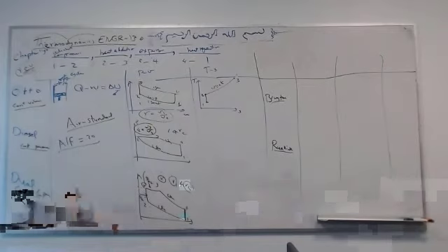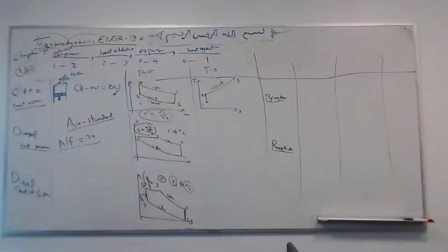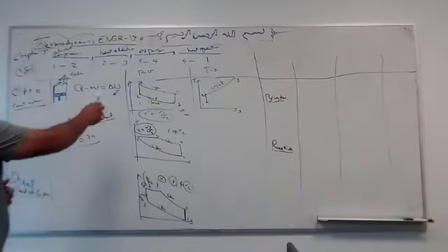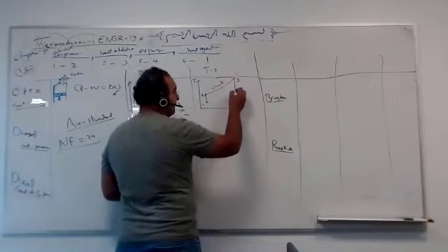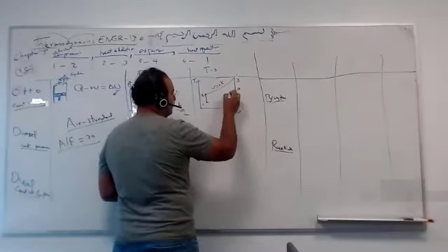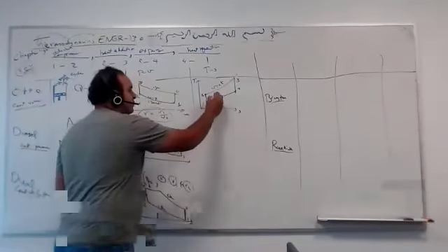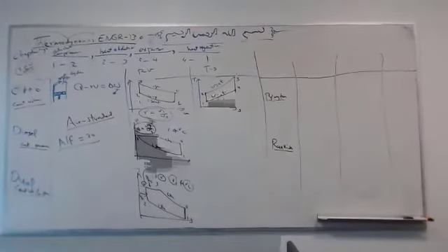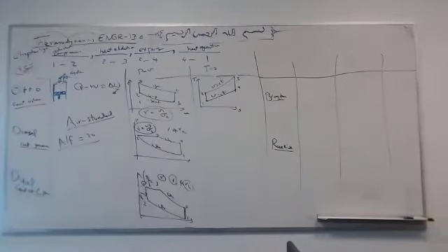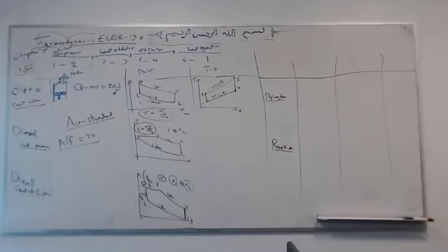Okay? How about 3 to 4? Always what here for these 3 cases? Reversible adiabatic. Exactly, which means constant entropy. Exactly, which means isentropic. 4 to 1 is constant volume. What's your name? Yihal, Y-I-H-A-L. Okay, so let's summarize.